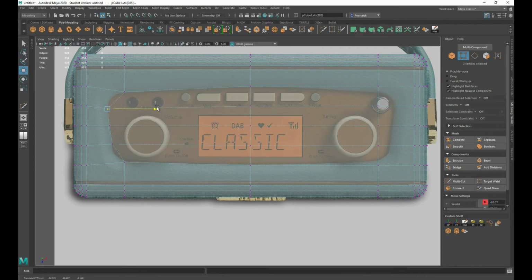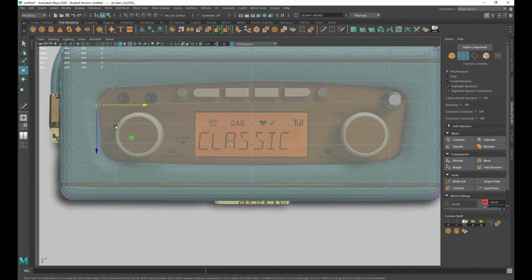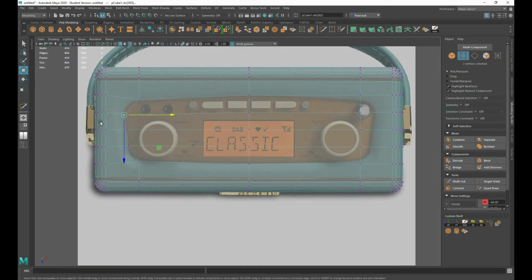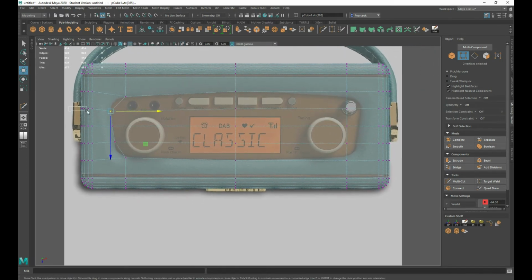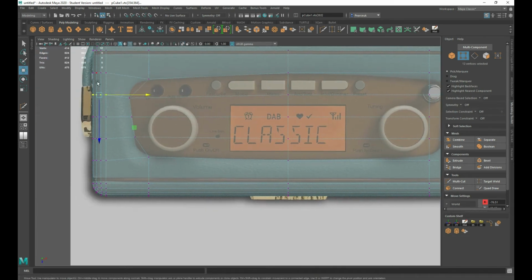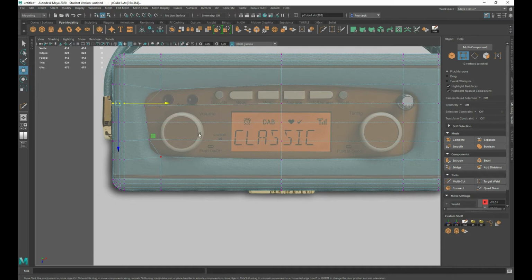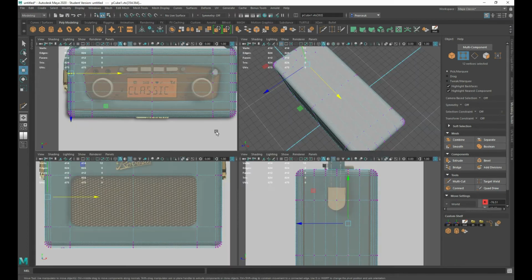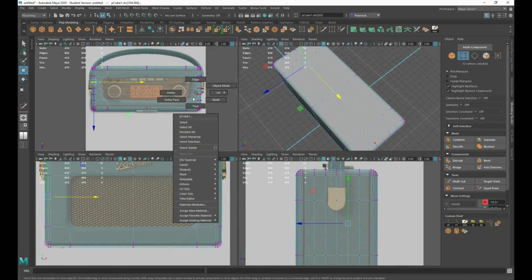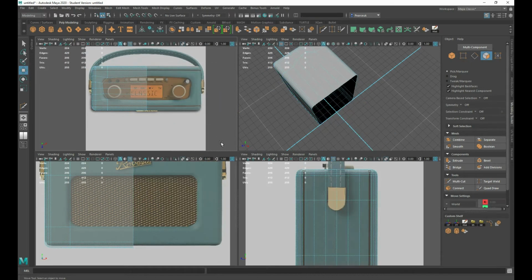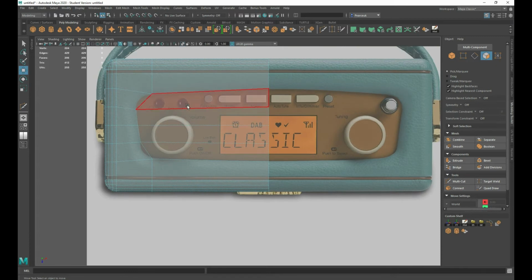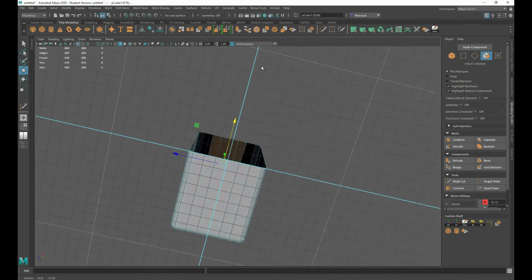Now I don't need this information underneath, but the high poly, this construction mesh, it doesn't matter how high it gets because we're going to bake that information down essentially. So I just want that information there at the moment. The other thing that I like to do is keep these kind of things straight. And at the moment you can see on the side it's all straight, and then it goes up. So actually that's fine. And then I'm going to want to bevel this. But first of all, I'm only working on this side at the moment. So I will at this point just delete this half altogether and then come in, and I'm going to select one and hold down tab and drag select those others because I don't want to select the ones on the bottom.